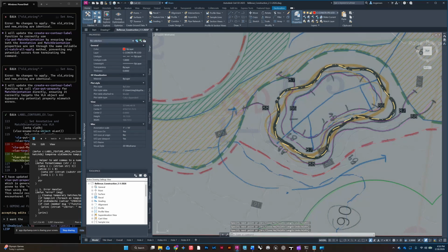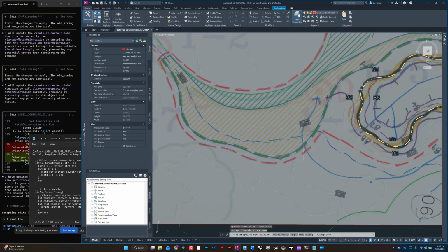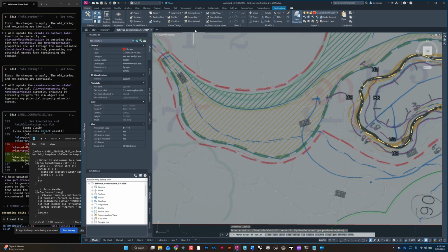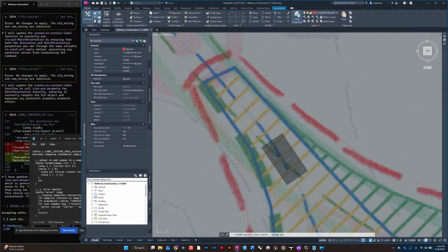So we'll go to there, spline, snap, a new polyline, endpoint. This one is also going to curve just along the outside of this fairway, this new fairway line, until we get to the sharp corner, spline, and snap to the end and to the end.